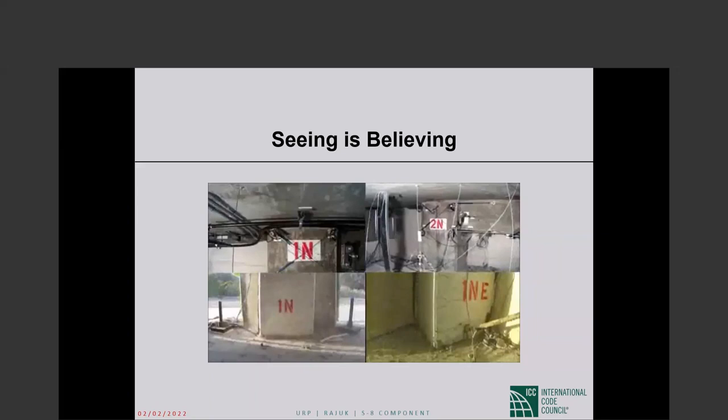However, if your design category is C or lower, then a flat plate column frame can be part of the seismic force resisting system. Now you may, if you want, do without column line beams.